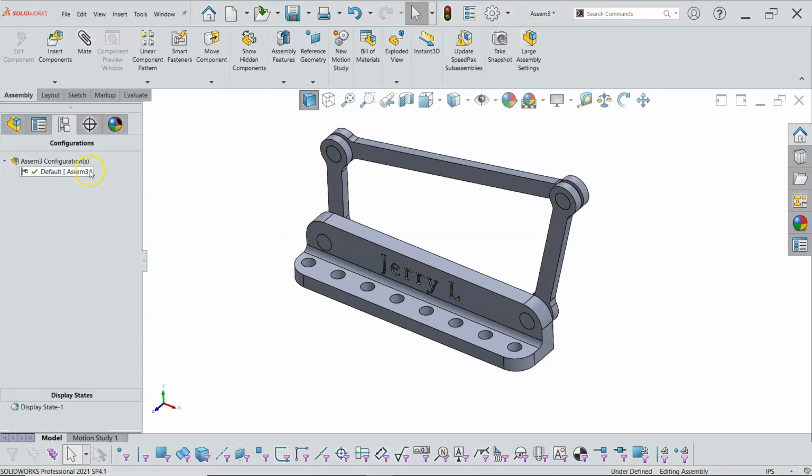The exploded views live under the configurations tab, and so we can have a configuration within a part that drives geometry, and we can have configurations within assemblies that control things like position, our static, dynamic, suppression states of do parts show up or not, and then also within the display states, if they're tied to the configuration, then we can control things like the visual properties, the colors, the textures, some of those more artsy style of with the components.